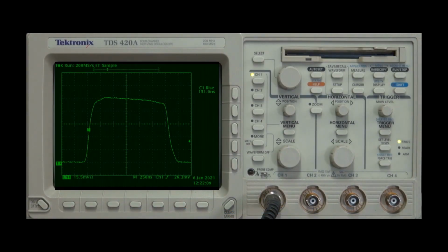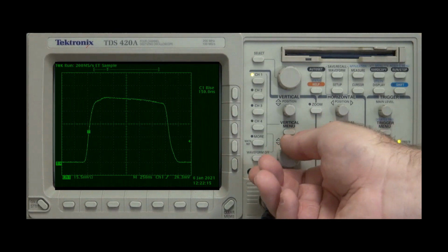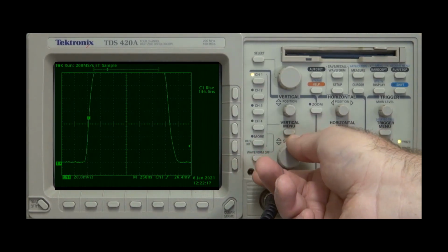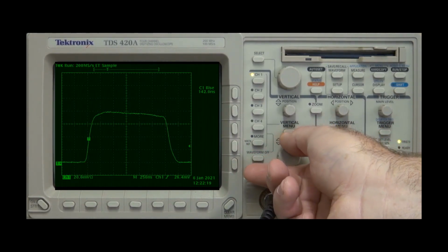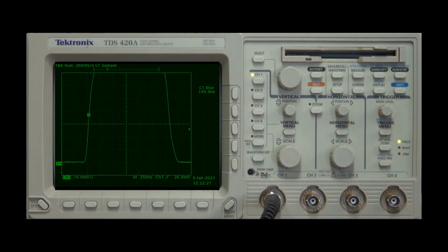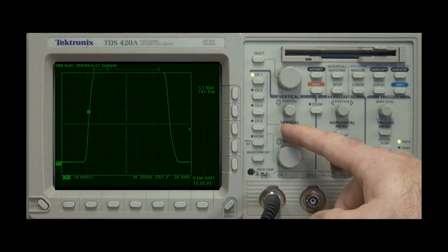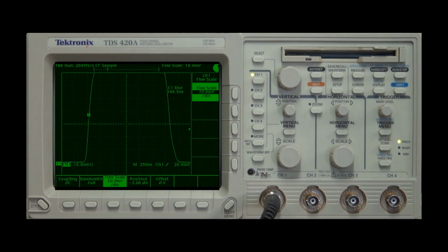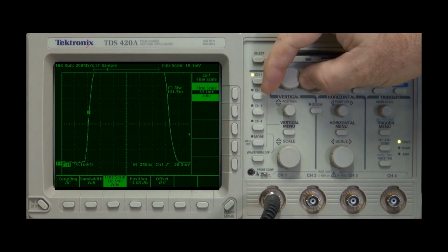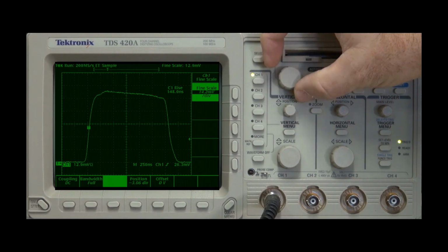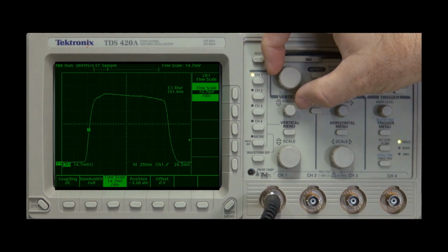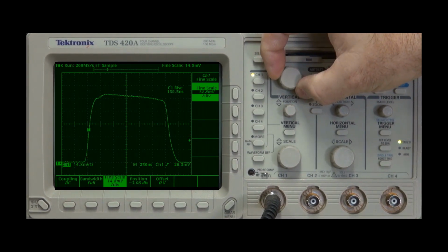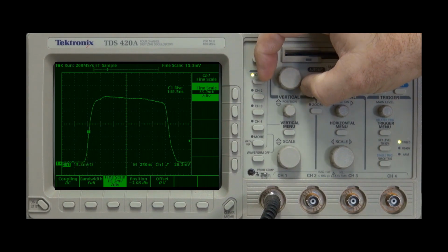We're using a digital scope, so it's not marked with the 10 and 90 or the 0 and 100s. We're just going to have to use each division's equal to 20%. First thing we're going to need to do is we're going to need to get our waveform to equal 5 divisions to represent 100%. So we're going to select our variable amplitude, and we're going to set it for 5 divisions. And we'll call this 100%.